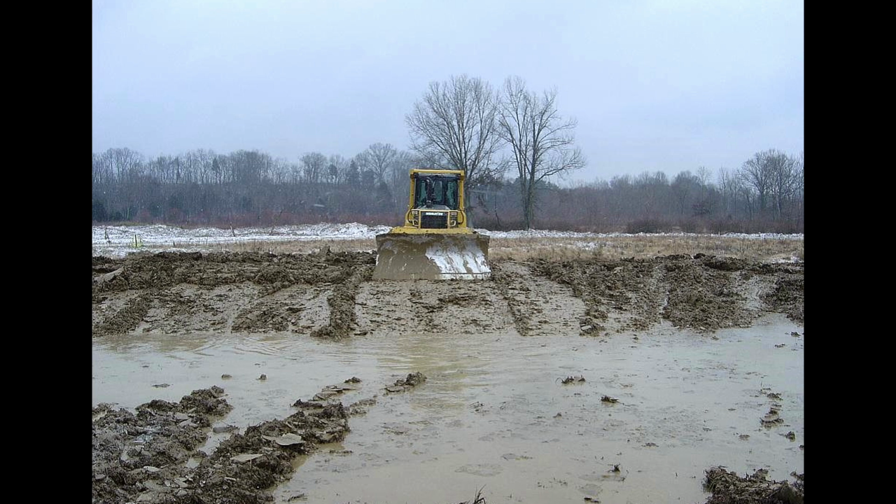Here an oxbow-shaped emergent wetland is being restored at Dix River by moving frozen soil. The technique worked well as the soil could not be compacted because it was frozen. We did not want to compact this soil because these wetlands were designed to collect runoff and then to inject this runoff into the ground.